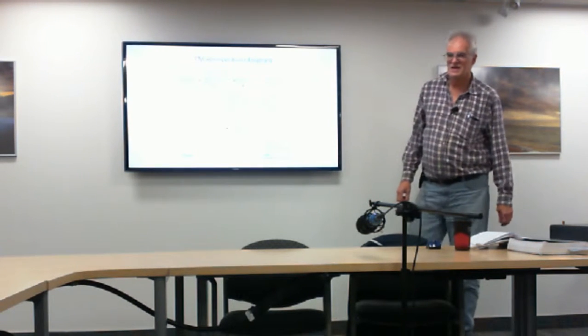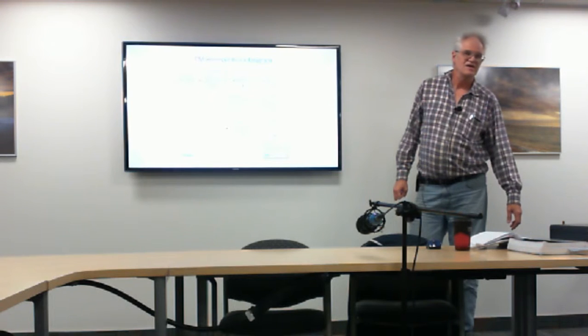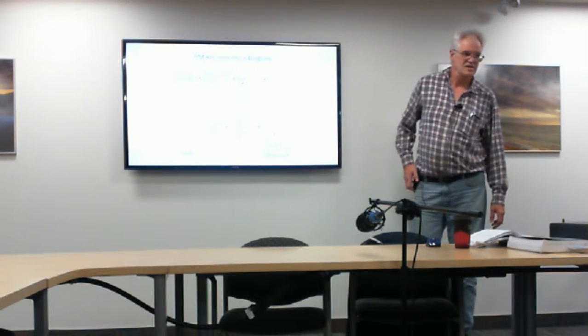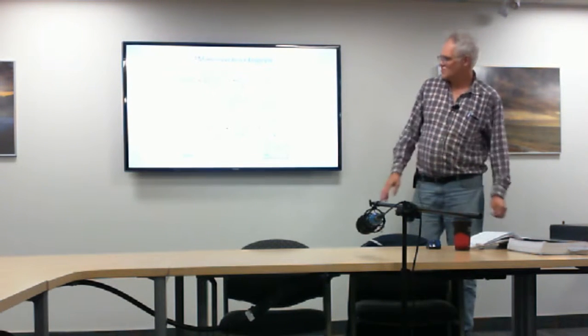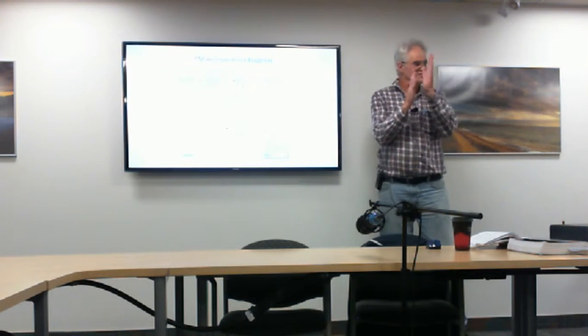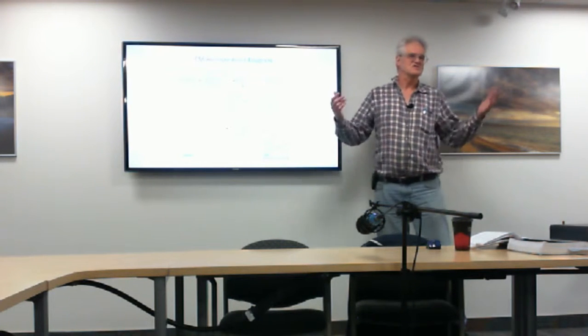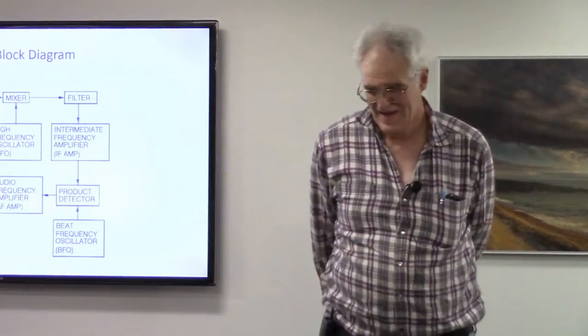So single sideband would not work without a beat frequency oscillator. It needs a BFO. You need something to subtract from, so you've got to reinsert that carrier. Otherwise, you're sitting with that sideband from 7 megahertz plus 300 to 7 megahertz plus 3000, but no way to recover it. Now if you've got a CW signal coming in, the difference, yeah, that's probably part of your selectors.